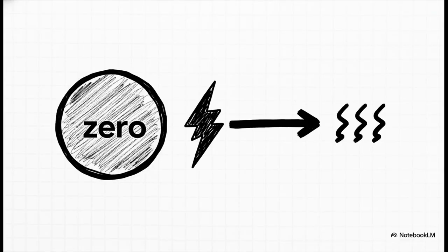And then we have the zero sequence network. Now, this one is kind of unique. It's internally free of the fault point itself. In this network, the flow of current is caused entirely by the voltage at the fault point. It's essentially a strict cause and effect relationship, you see. Zero sequence current only flows here because that specific fault point voltage has suddenly appeared out of nowhere.